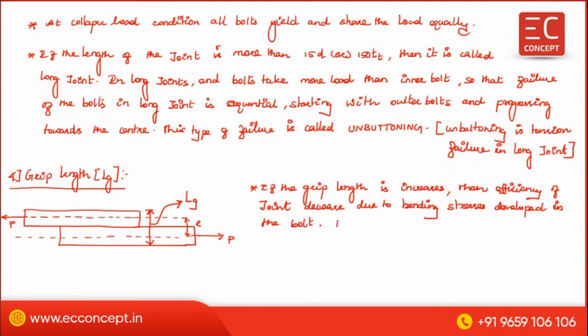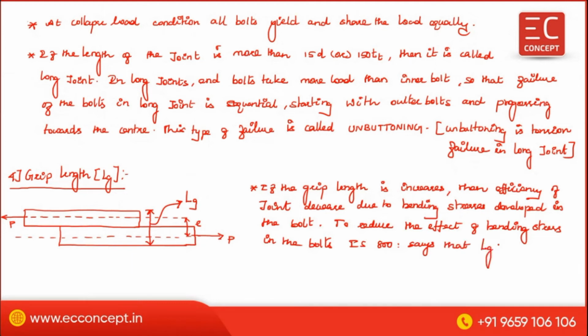To reduce the effect of bending stress in the bolts, IS 800 says that LG should not be greater than 5D.